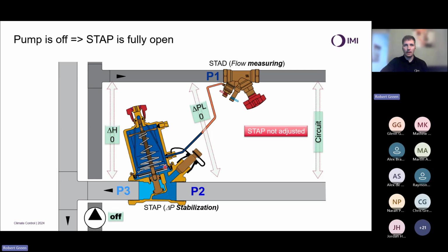And then this is my plug, which moves when my diaphragm is moving up and down. We're going to be opening and closing this plug to dynamically change how much differential pressure this STAP or DPCV is removing from the system. And finally, last but not least, we have my spring. In the case of a DPCV, the spring is on an adjustable platform, so I can adjust that spring force. What that spring is doing is physically pulling the seat and diaphragm open.